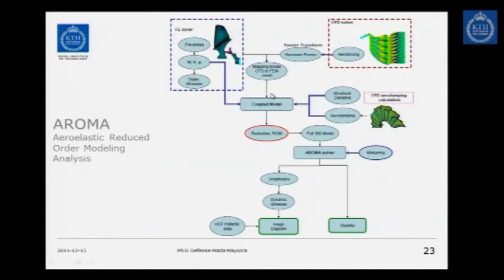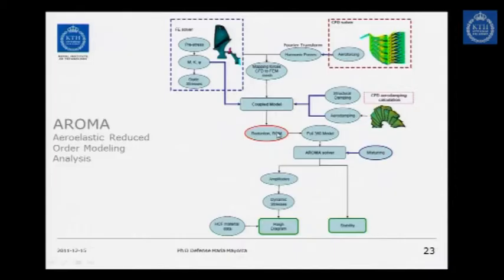We allow importing structural damping in the sense of linear damping, in terms of the critical damping ratio. But we also allow introducing the aerodynamic damping, either as a single value or as an aerodynamic spring. Then we introduce a reduction model. In this case, it's a Gaussian reduction model, where we can assess mistuning.